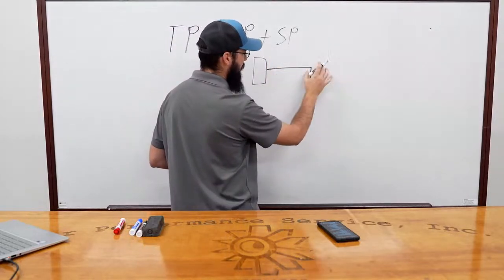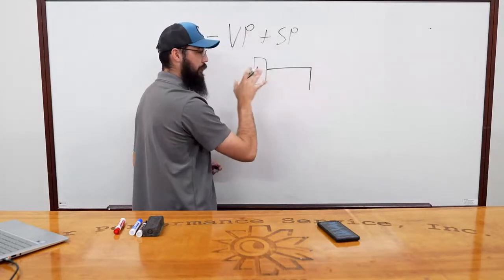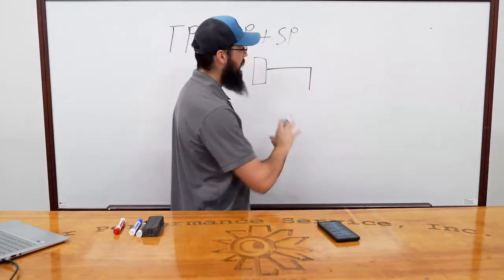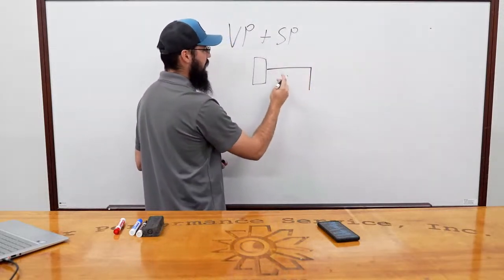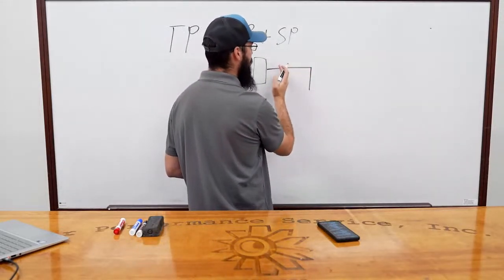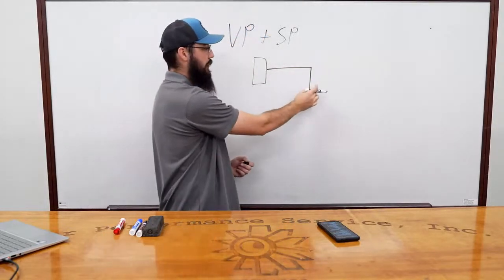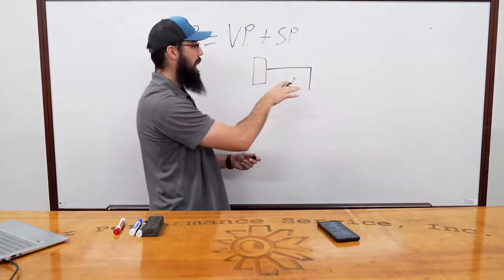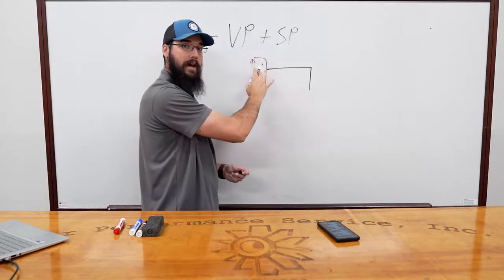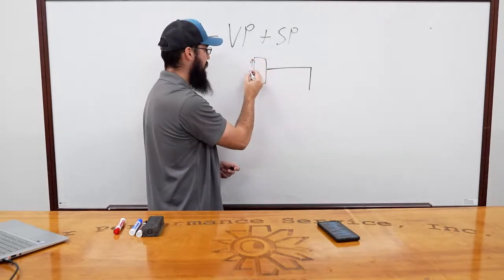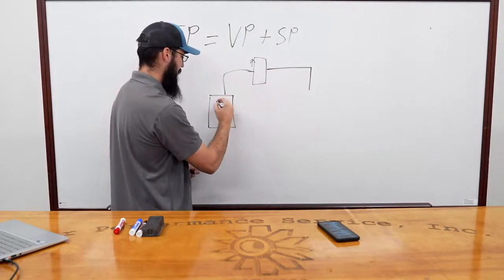You'll have a piece of tubing, a lot of times aluminum, that'll stick into like a 1/4 inch or 3/8 hole in the side of the system. And then it's got a series of little holes in it. Those holes will typically only be on one side of the pitot tube, or they'll be down here in the tip of the probe. And you may even have an airflow indicator back here where the magnet is, and you'll have a tube coming out of this over to a manometer giving you a reading.